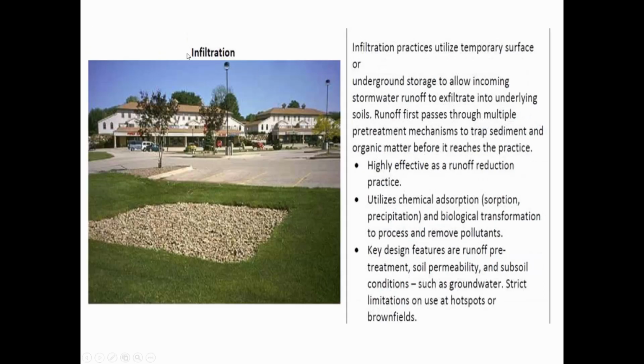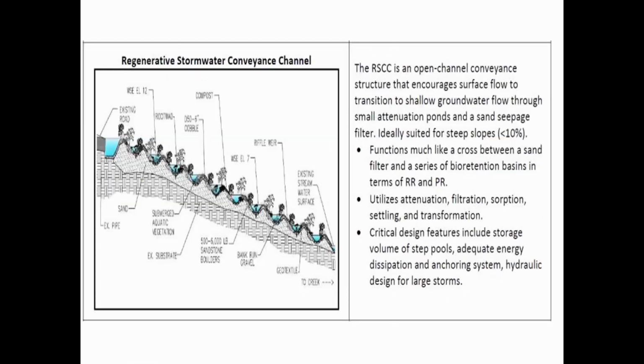Okay, here, just promoting new ways of having additional infiltration. What this is showing is a local pond in a commercial development where the runoff from this parking lot is going towards the pond, and what they've done is they've dug out the center of the pond and amended the soil there. Instead of just having whatever soil it was initially, they've put in gravel where the water can seep down to the subsurface more easily.